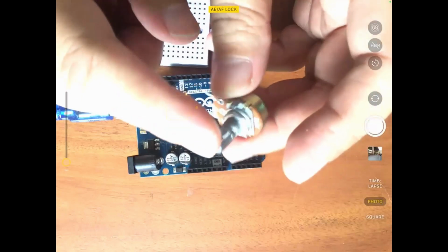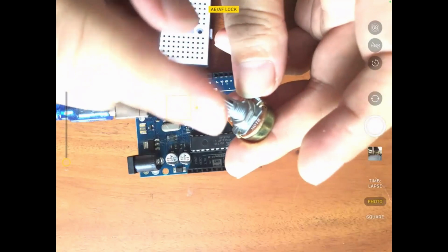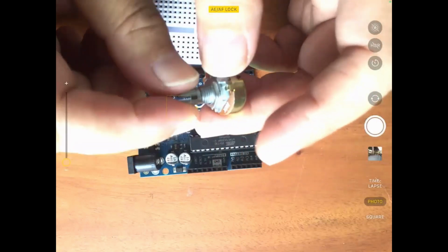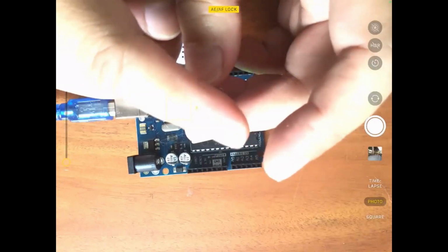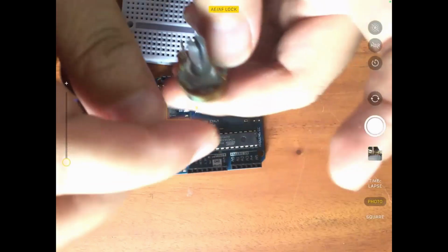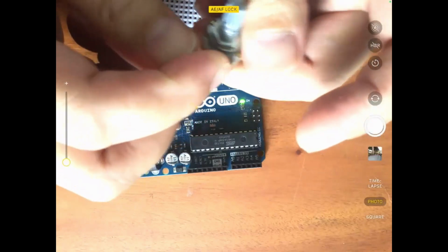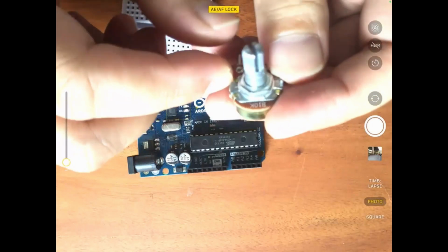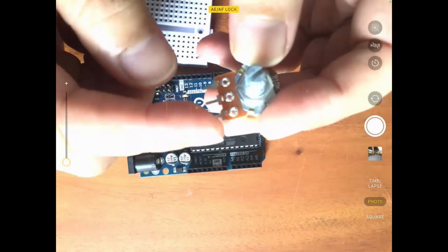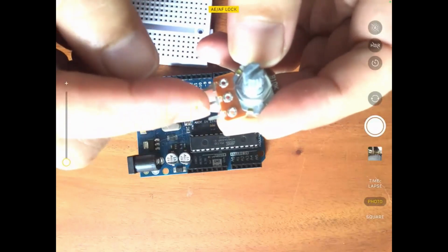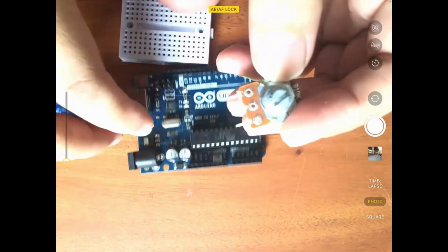And there's a conductor that touches the coil, and it is attached to the shaft or to this knob, no? And so as the knob touches part of the coil, parang nadidivide niya yung resistor dito at saka dito. Okay? So essentially, if you tap here, this is connected to 5 volts, this is connected to ground, and you tap here as the output, you have an adjustable voltage divider.